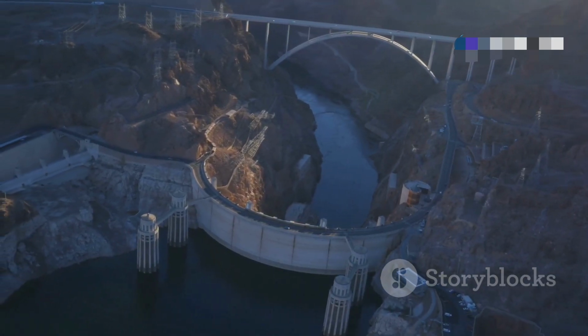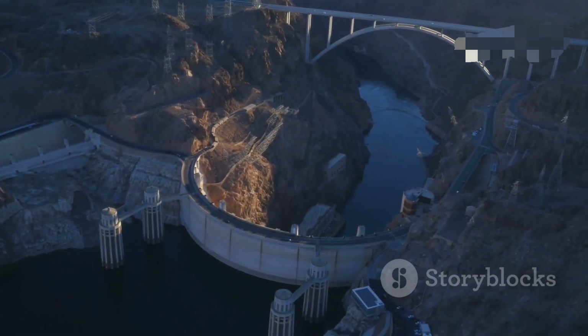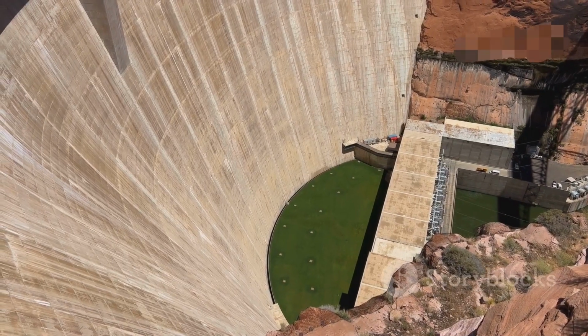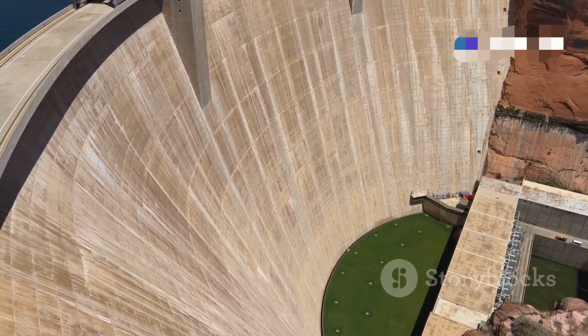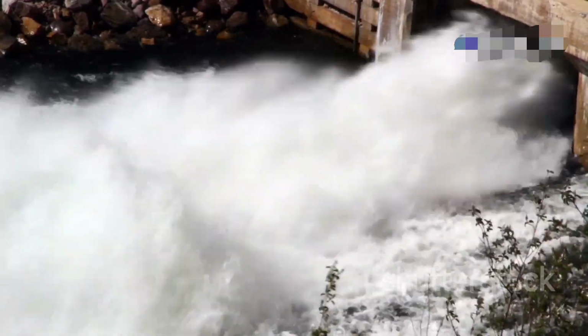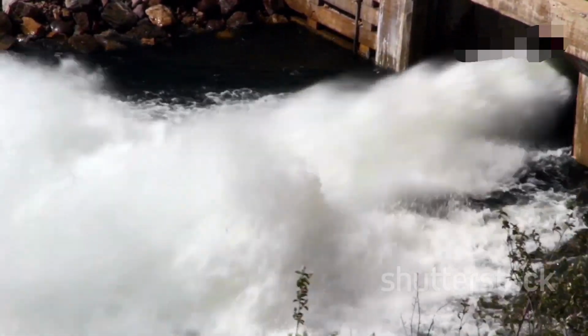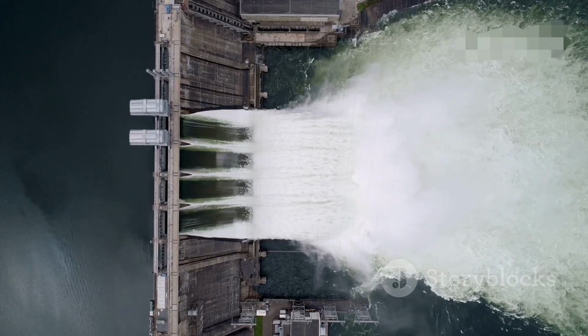These breach parameters are not entirely independent of each other. They are often interrelated. For example, the material a dam is made of will influence both the likely dimensions of the breach and how quickly it forms. A dam made of easily erodible material might develop a wide breach relatively quickly. Conversely, a more resistant structure might result in a slower, narrower breach.